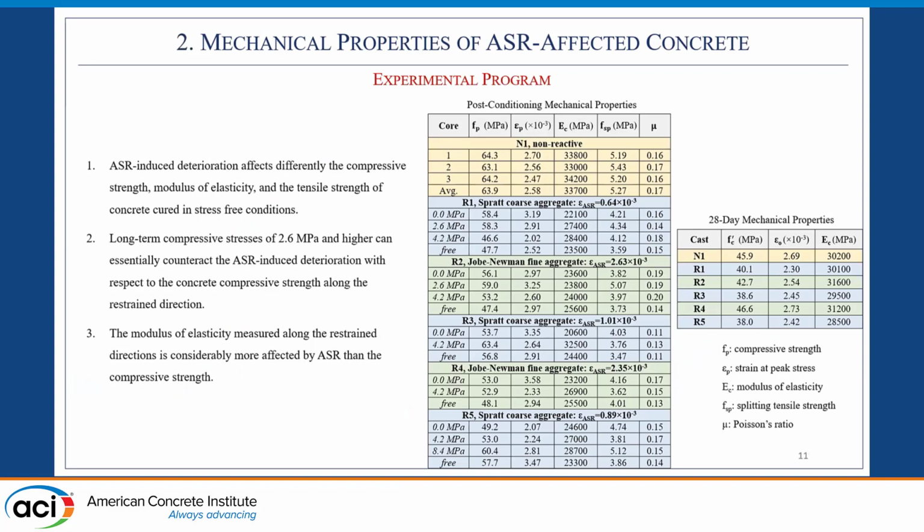Some of the important conclusions that we could make after this test were the following. The ASR-induced deterioration was found to affect differently the compressive strength, tensile strength, and the modulus of elasticity of concrete cured in stress-free conditions. Long-term compressive stresses of 2.4 MPa and higher can essentially counteract the ASR-induced deterioration with